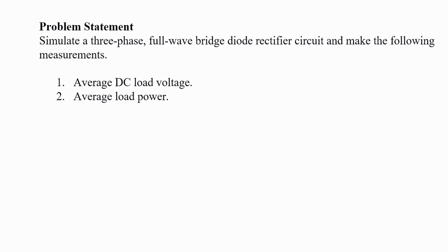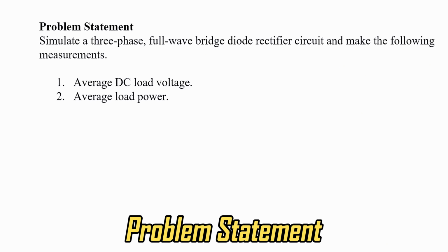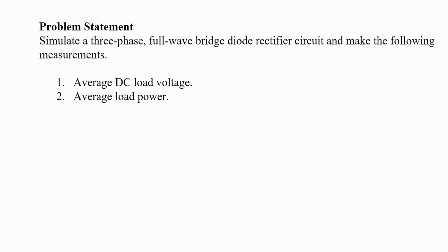In this tutorial, we will simulate a three-phase, full-wave bridge rectifier in Simulink MATLAB. Problem statement. Simulate a three-phase, full-wave bridge diode rectifier circuit and make the following measurements. 1. Average DC load voltage. 2. Average load power.